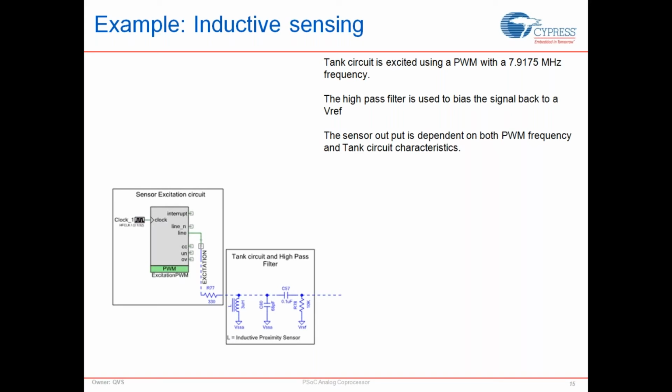I'm sorry, the other way. So 1 out of the 32 phases of the clock, I'm going to have 1/4 of the divider, and 31 of the other phases, the rest of the phases, I'm going to have 1/3 of the division. So effectively, over the entire phase of 32 clocks, I'm going to get a 3 and 1/32 division of the clock.